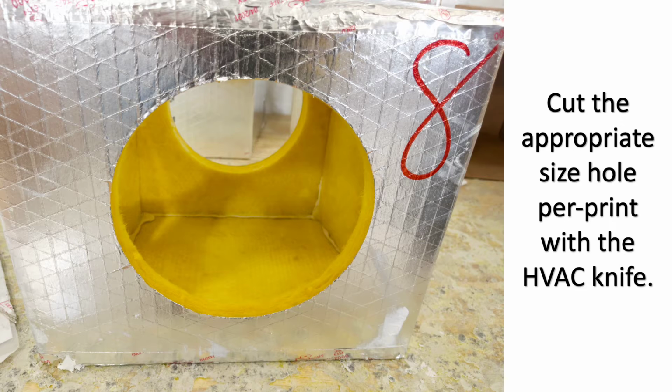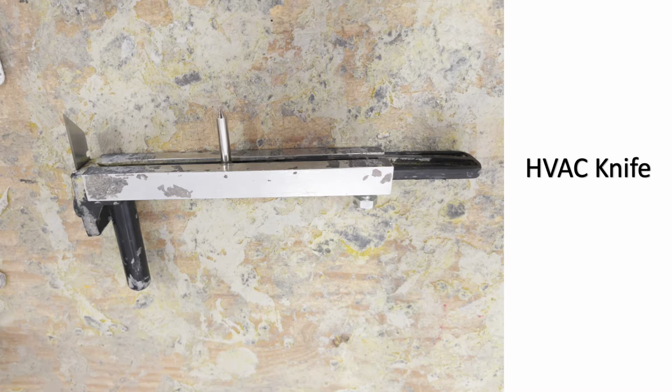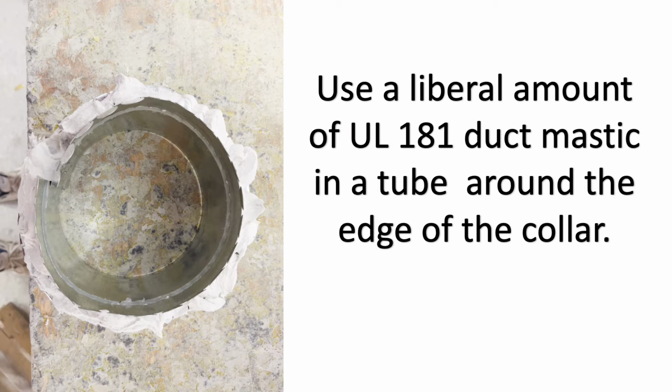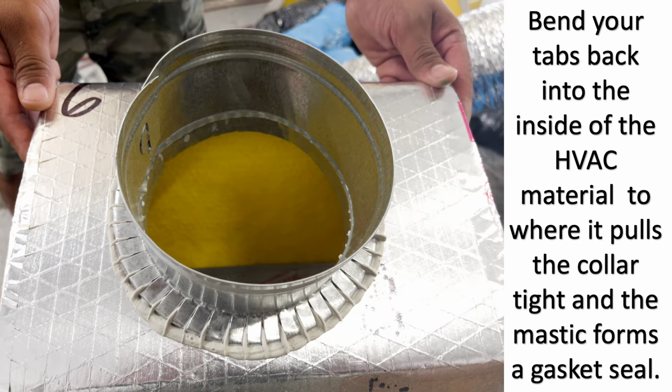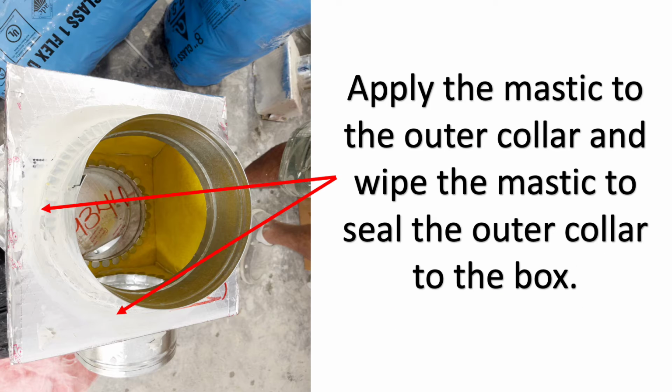Cut the appropriate size hole per print with the HVAC knife. This is an HVAC knife. Use a liberal amount of UL 181 duct mastic in a tube around the edge of the collar. This is UL 181 duct sealant in a tube by LaSalle. Bend your tabs back into the inside of the HVAC material to where it pulls the collar tight and the mastic forms a gasket seal. Apply the mastic to the outer collar and wipe the mastic to seal the outer collar to the box.